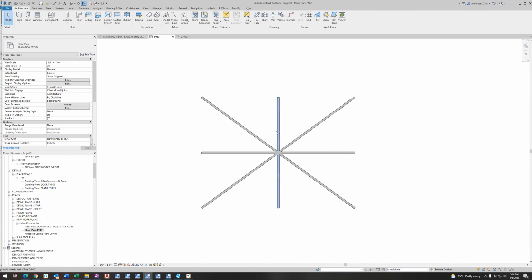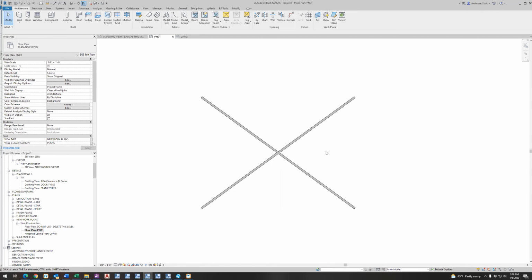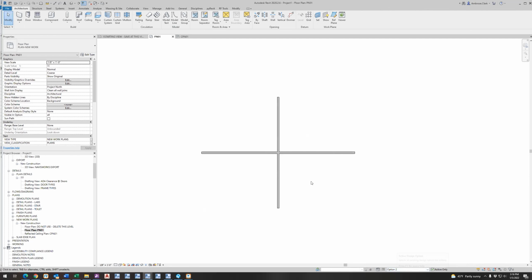We go back to main model. I can set these plus ones to add to set, option 2. And now they disappear. The main model only shows the primary option. So if you want to see option 2, you have to switch to it. And now you're editing option 2. And this is where it gets a little tricky.